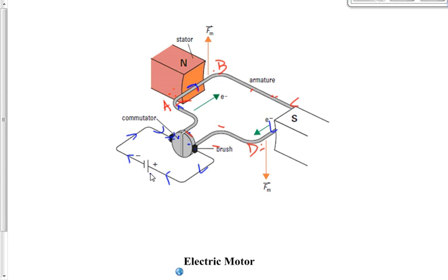We've got an electric current going from A to B. We've got a magnetic field going this way, towards the right. If we have a current going from A to B and a magnetic field going towards the right, then the magnetic force on wire AB is going to be upwards, right? So wire AB will be pushed upwards.